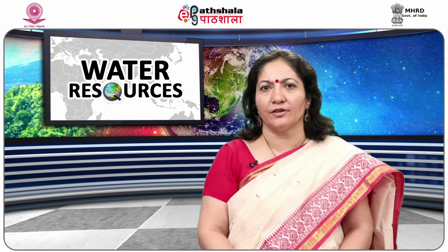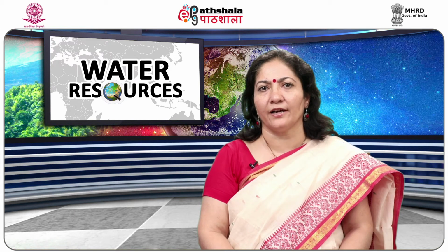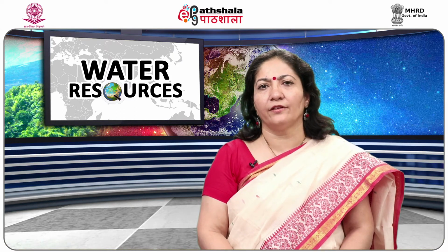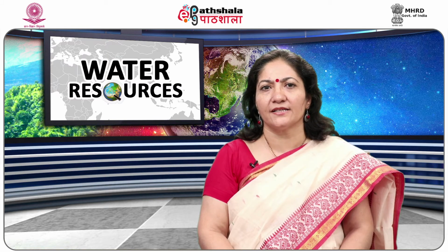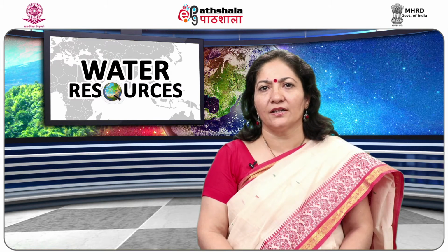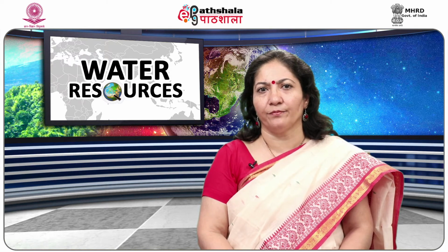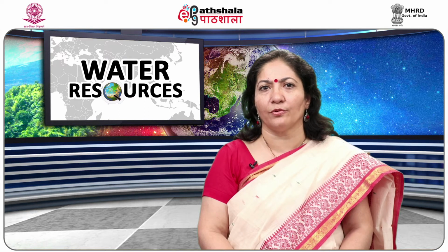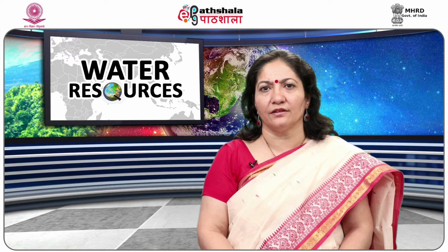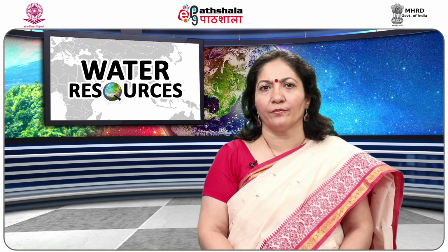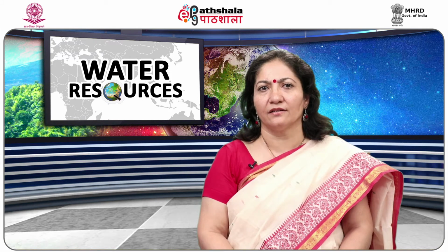Highly fractured igneous and metamorphic rocks, however, could have a high secondary porosity. It is depicted in figure number 9, which shows the rock with porosity increased by fracturing. The arrangement or packing of the soil particles plays an important role in porosity. If the particles are stacked directly on top of each other, it is called cubic packing. It has higher porosity than the particles which are laid on top of two other particles in a pyramid shape, called rhombohedral packing. The smaller particles could fill in the void spaces between the larger particles, which would result in a lower porosity. See figure 10a and 10b.